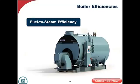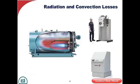Now, if we look at various boilers, those convection losses can differ anywhere from 0.5% to 2%. In other words, in a large fire tube boiler like this, it could be 2%, 1.5%. On a small little vertical fire tube like this, might only be 0.5 or 0.75%. It depends upon the mass. Now remember, when we measure radiation and convection losses, and the reason I mentioned turn down before when I talked about thermal efficiency, is it's all based on input, all right?